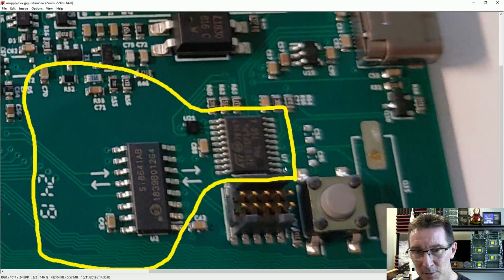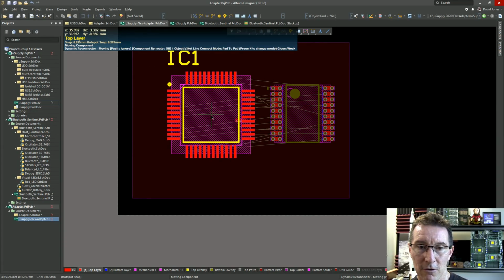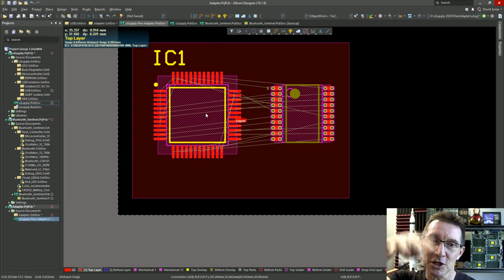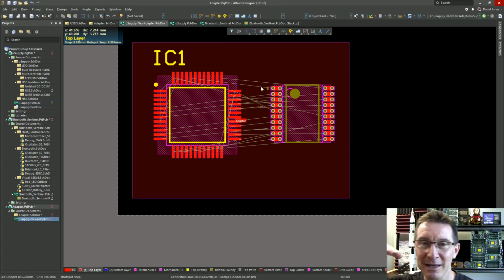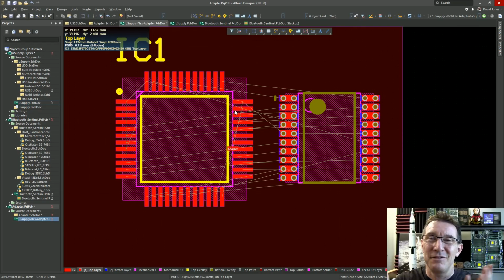So even if we butted the pins right up against here, we do not have the room to fit the chip in there. You can just physically tell. Okay, so let's allow for some flex, because once you've got the chip on there, the chip doesn't really bend. So this flex underneath this chip isn't going to bend. We want to add some bend radius so we can come up over that resistor, and then put some insulating stuff on the bottom and stick it down with some elastic or double-sided tape or something like that. You can just leave it flapping around in the breeze. Doesn't matter. It's just a prototype. This is not high-speed stuff.